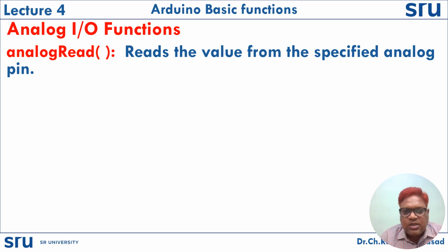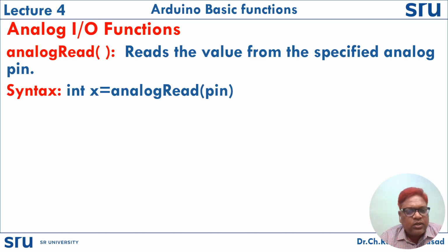If you have connected any sensor, that sensor value is read by this analogRead function, and the syntax is int x = analogRead(pin), where this x value depends on the resolution. I already mentioned in lecture 2 that all analog inputs A0, A1, A2, A3, A4, A5, these 6 inputs, are of 10-bit resolution.